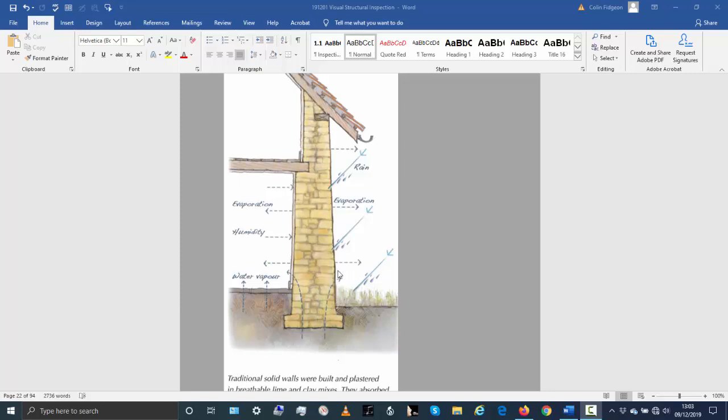So it will evaporate throughout the front wall. Generally not so much through the internal wall, because you'll have more wind movement out here. So most of it should go to the external wall. So in short, it's a breathing wall where moisture that comes in will dry out through evaporation. Now, I'll also point out here that, oftentimes let's say there's just flagstones or paving stones that were put down internally, and water vapor would just evaporate through those stones as well.